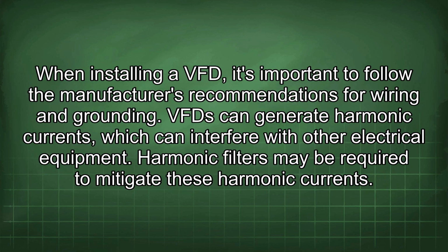When installing a VFD, it's important to follow the manufacturer's recommendations for wiring and grounding. VFDs can generate harmonic currents, which can interfere with other electrical equipment. Harmonic filters may be required to mitigate these harmonic currents.